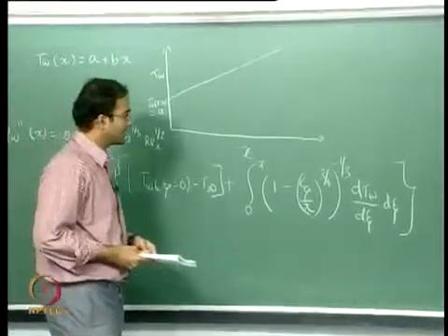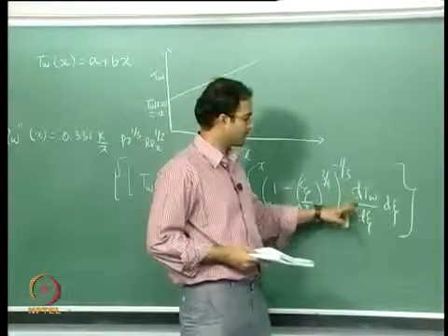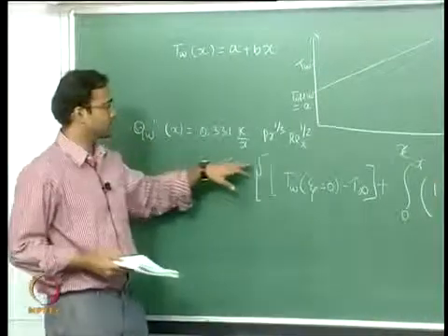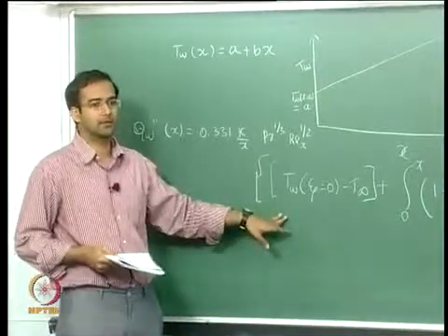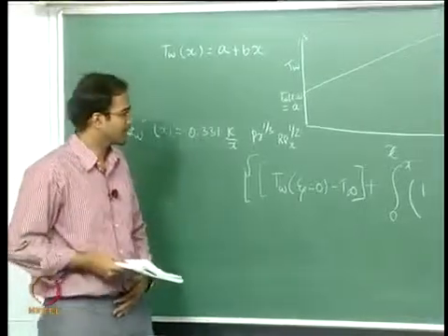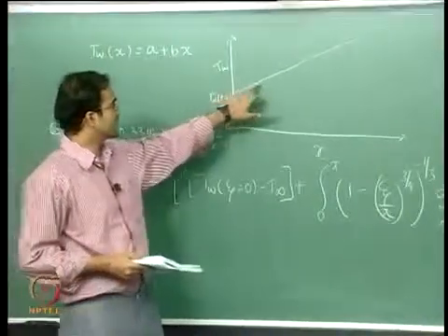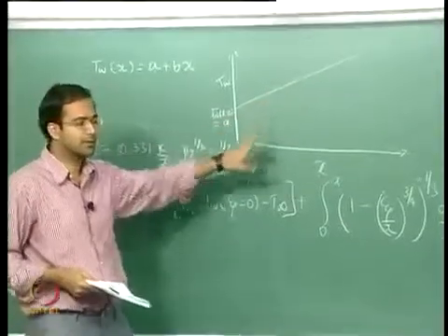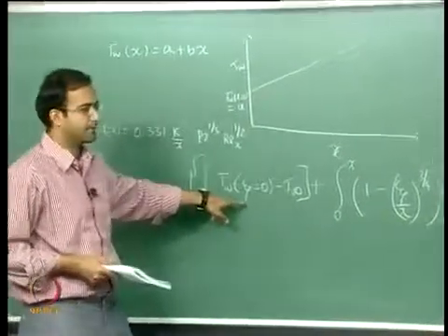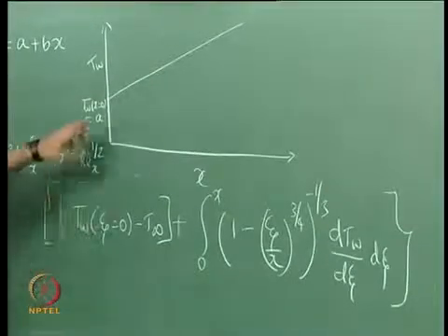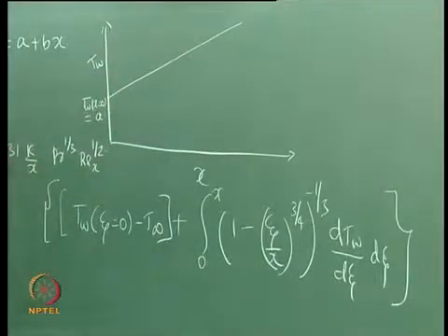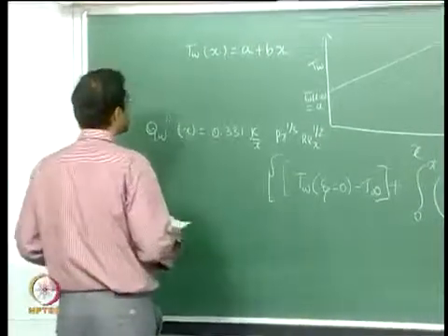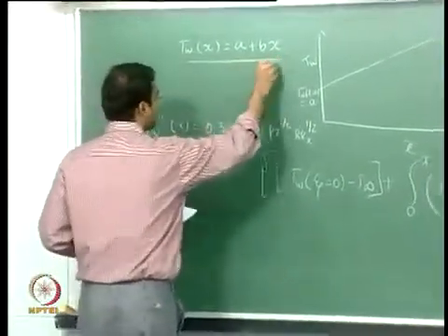Now for the limiting case where you do not have any slope, the slope is 0, so this is T wall minus T infinity, and this becomes equal to your flat plate with a uniform temperature expression. Okay. So of course if you have continuous variation but also intermediate temperature jumps, there you have to introduce an additional delta T into h for those temperature jumps in between. Okay. So apart from that, this is the expression. Now we will substitute for the given temperature profile whatever we require.